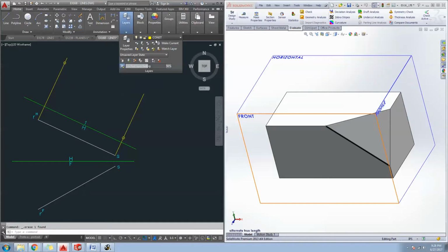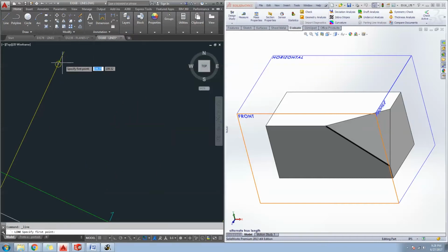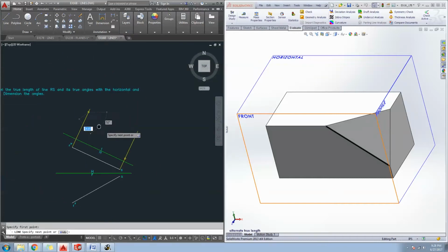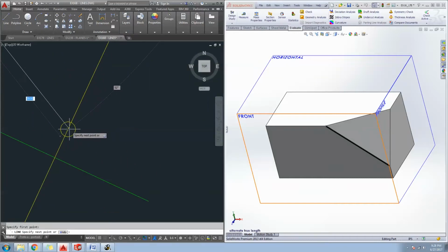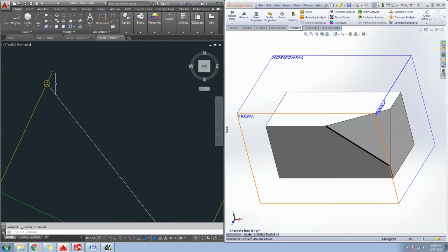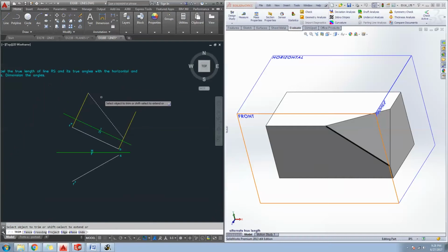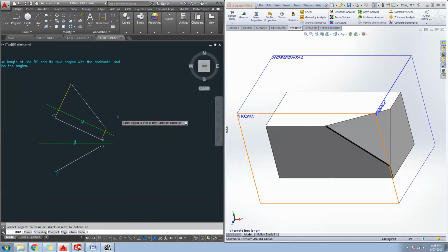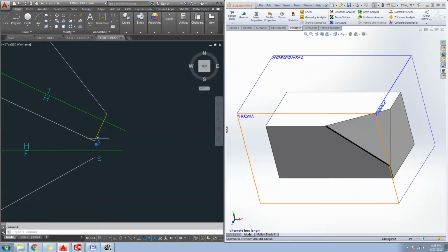We're going to move over to the object layer. We're going to draw a line from the center of that point right to there. We'll delete the circles. And we're almost there. I'm going to type trim for the trim command, use that guy as my boundary, and get rid of those. And we're ready to borrow some text.